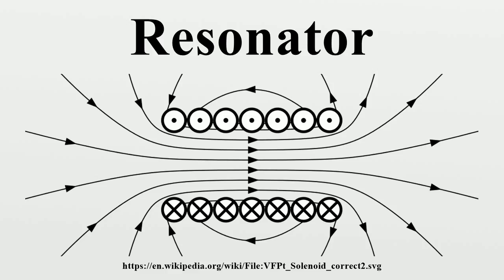Automobiles. The exhaust pipes in automobile exhaust systems are designed as acoustic resonators that work with the muffler to reduce noise by making sound waves cancel each other out. The exhaust note is an important feature for many vehicle owners, so both the original manufacturers and the aftermarket suppliers use the resonator to enhance the sound in tuned exhaust systems designed for performance. The resonance of the exhaust pipes can also be used to remove combustion products from the combustion chamber at a particular engine speed or range of speeds.